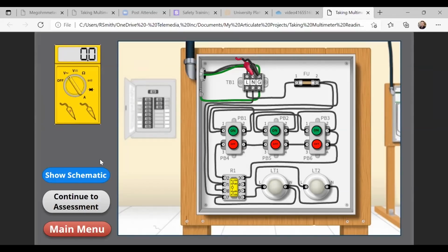Now, if for any reason we ever saw a voltage between neutral and ground, that means something is not quite right in terms of the direct connection between neutral and ground. So that can help us as well. One of the trickiest parts of electrical troubleshooting is when we start measuring a voltage across a neutral, from one part of a neutral to another, and start to see some discontinuity or some voltage buildup on a neutral.